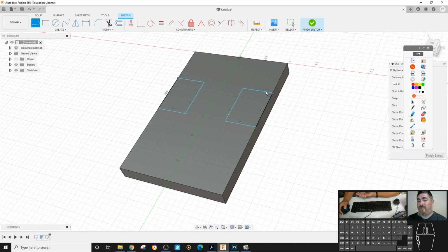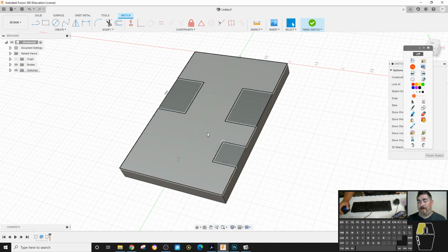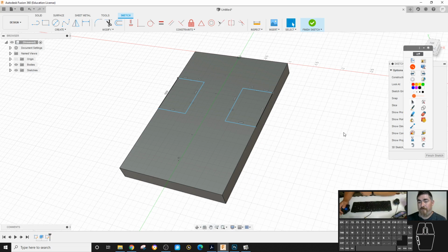And also that's why I like to use rectangles, because if I did lines, I'd have to make sure I got it locked in to be perpendicular. But now when I grab the corner, it's doing this. Things are not locked horizontal and vertical or perpendicular to each other. So now I have to add those constraints also. But by doing the rectangle, it does all that for me. So these 2 are here. They're moving correctly. That's good.